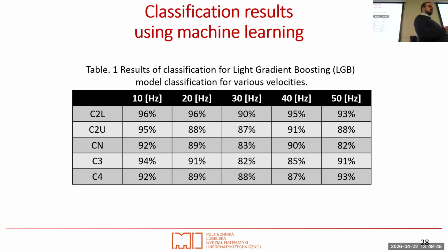That corresponds to 600 RPM in the system, because it was an AC current motor, and we were able to make some tests up to 50 hertz, so up to 3000 RPM. That was enough to test those bearings, because they were pretty big ones, not for electric motors, which rotate at much higher speeds, for example 20, 30, 40,000 RPM.